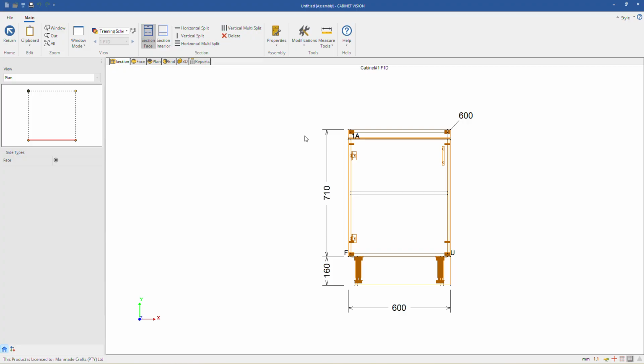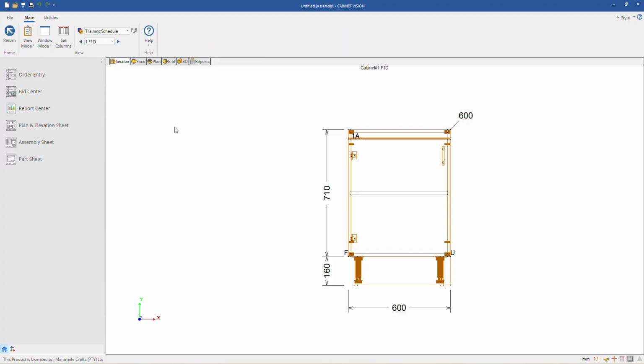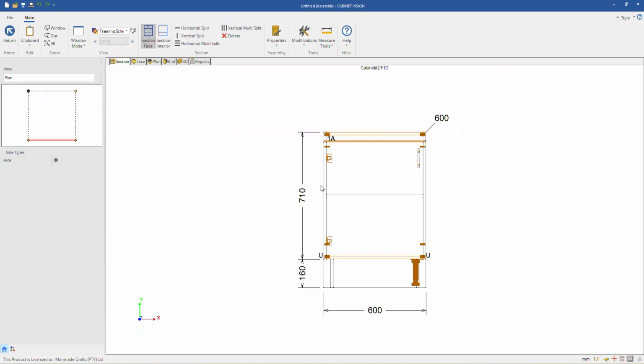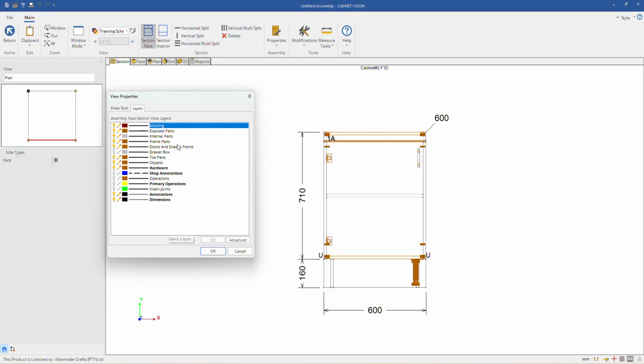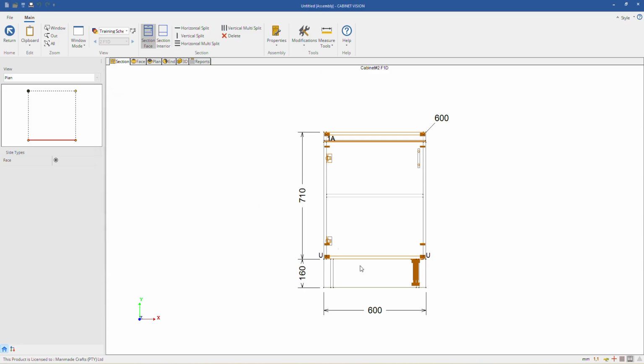And then from there, over time, build your own layer schedule. Which is the best view to actually play with it? Go into that specific view. Right click, properties, layers. Go and press buttons here. You can do the same thing with 3D as well.